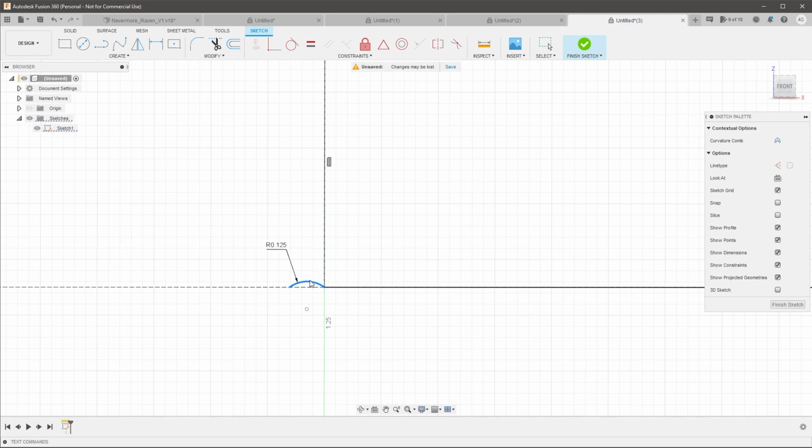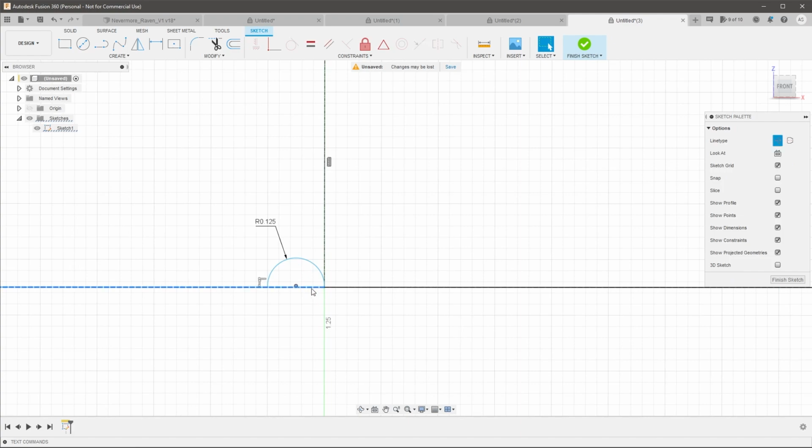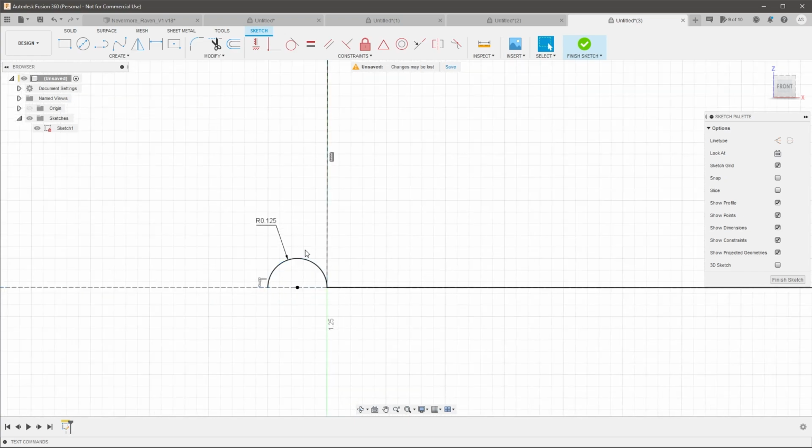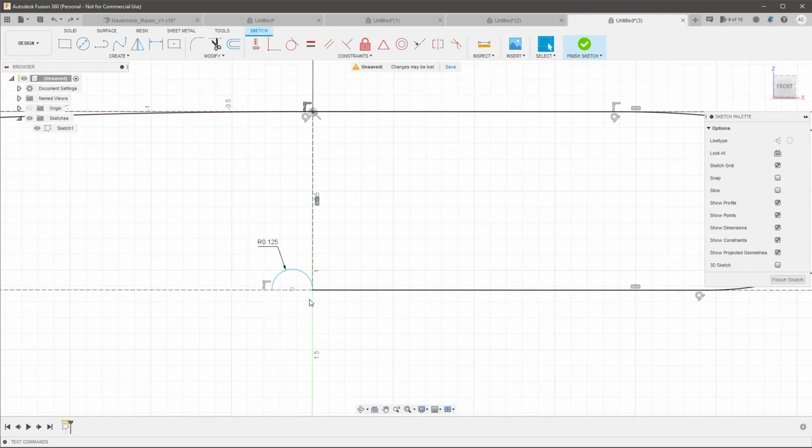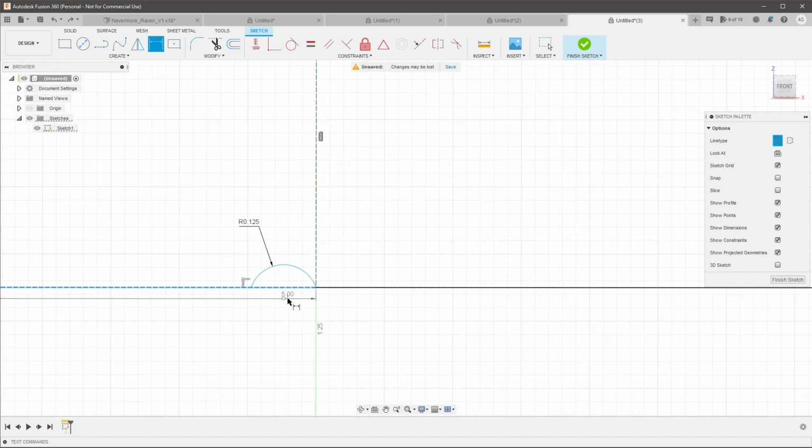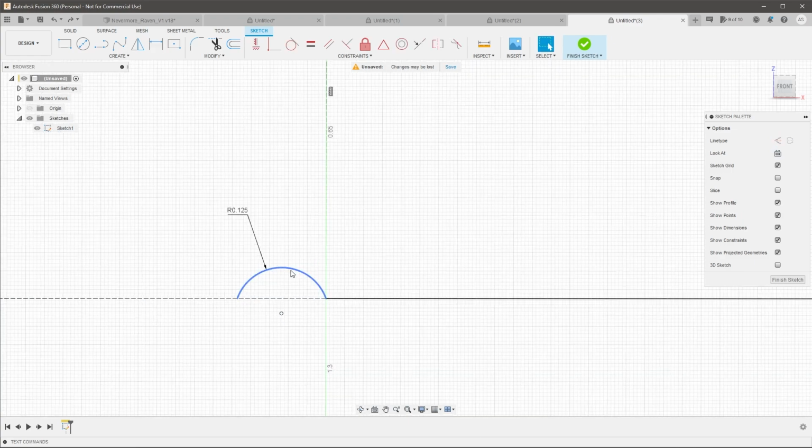And then how far into this blade am I going to carve that? Now, if I'm going to carve it exactly half of a circle, then I can take this center point line, click on the construction line, and make those coincident. So that means that exactly half of the circle will be notched into it. If I didn't want that, then I could give like a dimension from here to here. Or what I could do, which is a cool trick that many people don't know about, is you can dimension to the tangency of an arc.